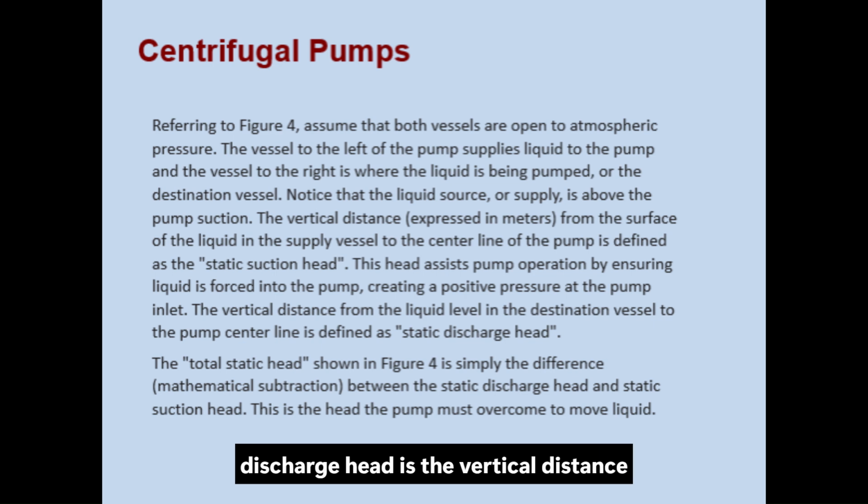The static discharge head is the vertical distance from the destination vessel liquid level to the pump centerline. The total static head is simply the difference between the static discharge head and the static suction head. This total static head is what the pump must overcome.